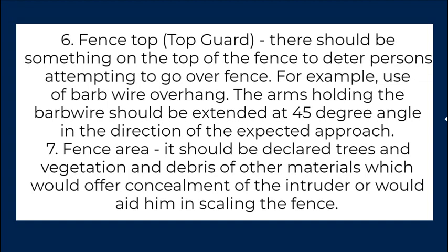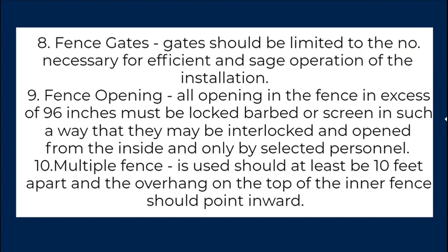7. Fence area. It should be cleared of trees, vegetation, debris, and other materials which would offer concealment to the intruder or would aid him in scaling the fence. 8. Fence gates. Gates should be limited to the number necessary for efficient and safe operation of the installation.